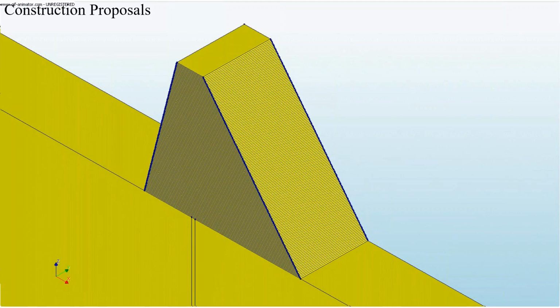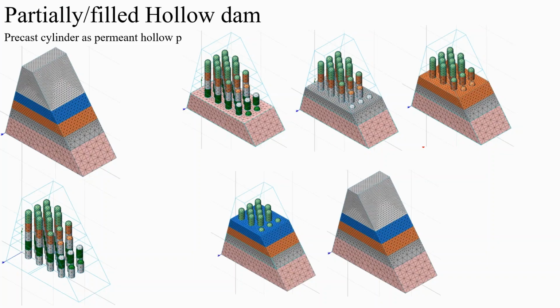Now, it is our recent work. We are working on a hollow type of them. We found that the construction of bubbles may be more complicated and it will affect the construction. And on the other hand, generating voids within the dam may reduce the factor of safety. So we think about generating slender voids. In these slender voids, we can fill them easily with infill material such as soil, for not affecting the factor of safety of the structure.